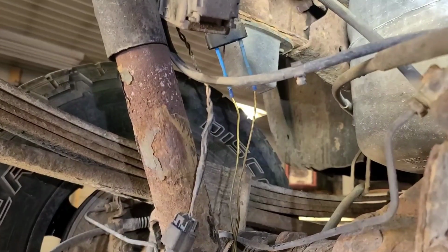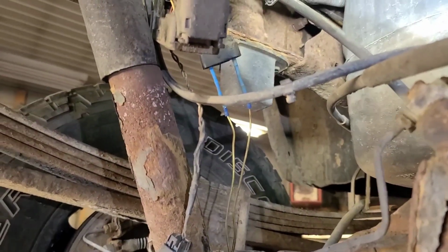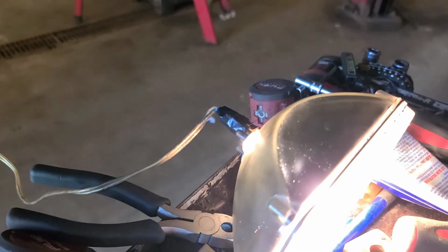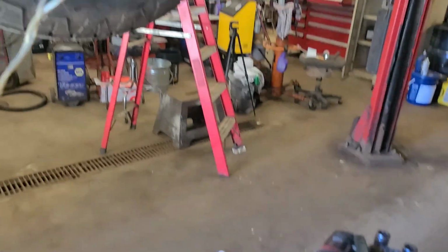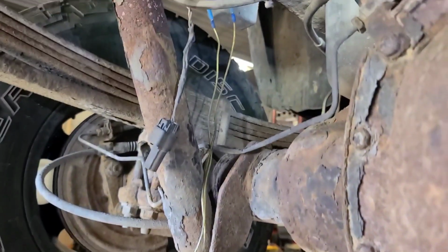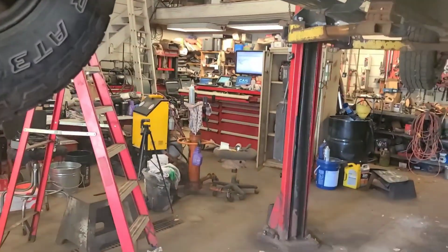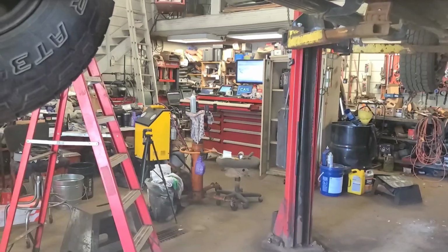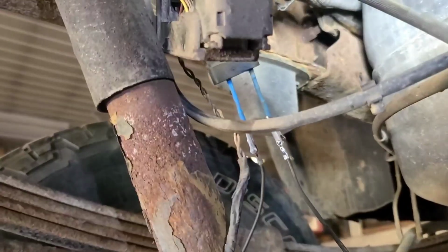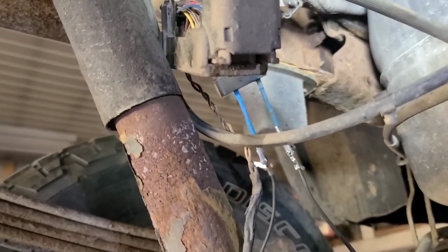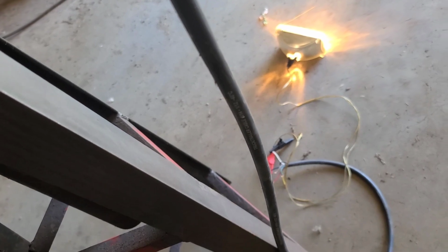So with the headlight connected across the red wire and the black wire at the relay, it lights that. So we're going to jump power from the red wire to the blue wire that goes to this plug back here and see if it lights a headlight. We've already checked the integrity of the ground on the trailer plug. So jumping the red wire to the blue wire at the plug sends power to the trailer plug-in, and I've got the headlight connected on the white and blue wires and it lights up.